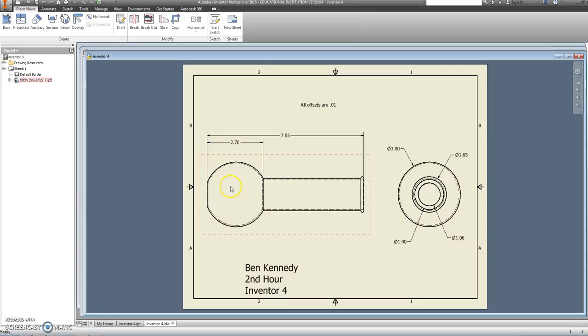So hopefully you learned how to revolve. You make anything around a center line and then revolve that around it. By offsetting that, I've created a cavity within it. You could make it solid if you did not do that. And hopefully you also learned how to do an offset. So I offset the distance in so that I had that cavity, and then also we revolved around the center line instead of an extrusion.